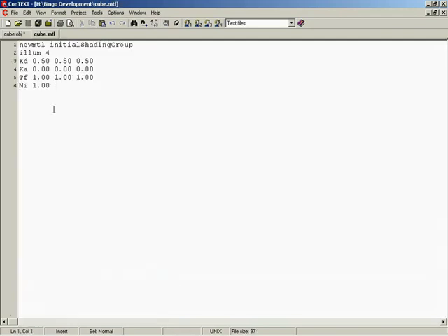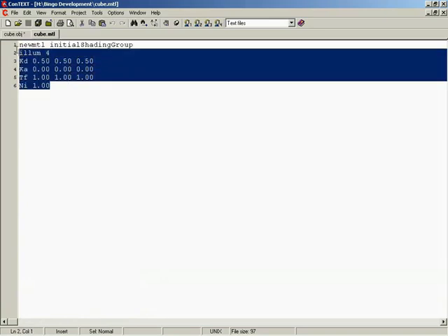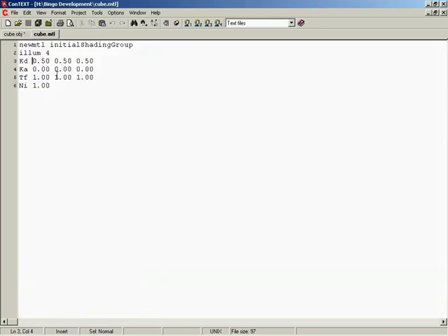If we come over to our MTL file, you notice the first line is again a command followed by parameters. We have our newmtl command, and then it specifies the name of our new material. Everything following that until another material is created are the parameters to this material. So our illumination is going to be 4. Our constant diffuse color is going to be 0.5, 0.5, 0.5, which is a medium gray. Right. And our ambient constant is going to be black. Our transparency is going to be full transparency. And we have our normal. Okay, shininess? Shininess, thank you. I saw the N and it just said normal. I gotcha. Yeah.